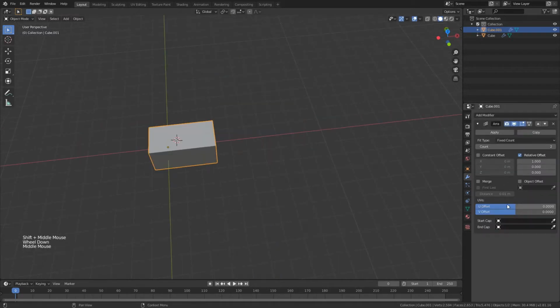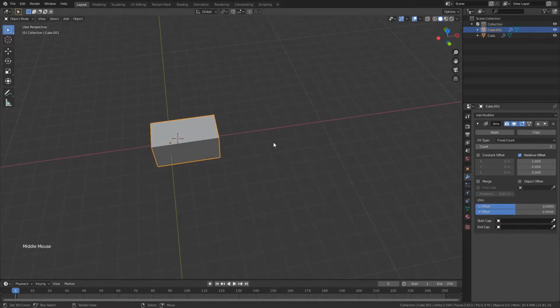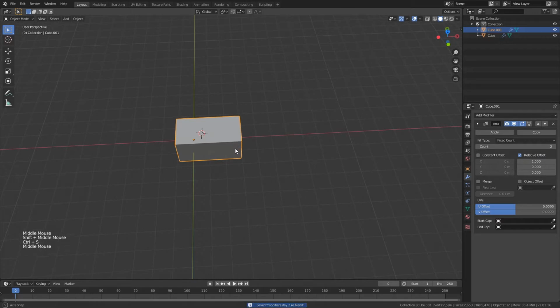All right, now let's keep this one aside over here and see some more parameters about this modifier. Each of these modifiers has two very important things. One is the object coordinate controller. Most of these modifiers have a controller you can assign, which is used for transforming the modifier, and one is the vertex weight. Okay, and we are going to discuss the vertex weight first after this modifier before proceeding to others.